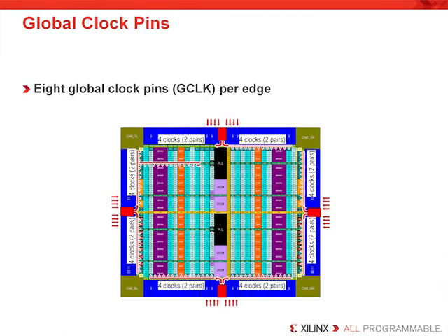Spartan-6 is a wire bond type device. This means that the I/O pins are distributed around the periphery of the die. This implies that each pin is associated with an I/O bank on the perimeter of the device, like the Spartan-3 device family, but unlike Virtex-5 or Virtex-6, which have I/O banks placed in columns throughout the FPGA. This also places some restrictions on clock input pins.